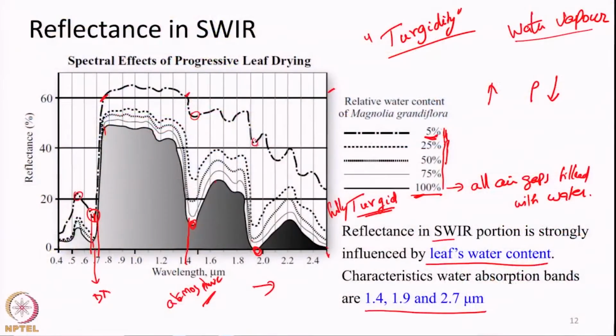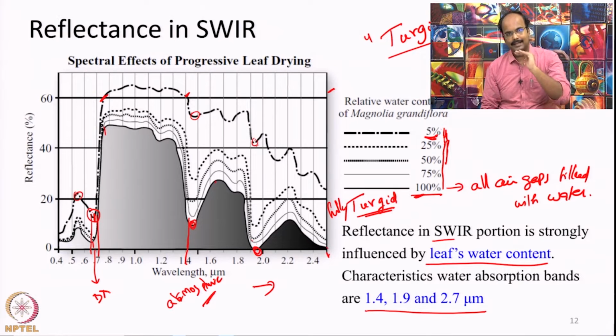Also, one more important thing to notice is the portion of EMR at which the transition occurs. Typically, the sudden increase in reflectance from red to NIR will happen around the red to NIR transition zone, that is around 0.67 micrometers to 0.72 micrometers. Within that very short range, where the wavelength transitions from the red band to the NIR band, this increase in reflectance will occur.